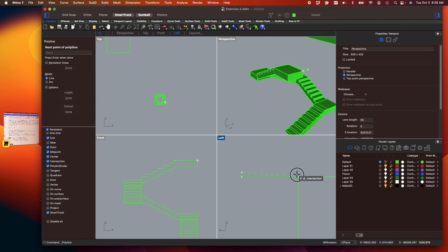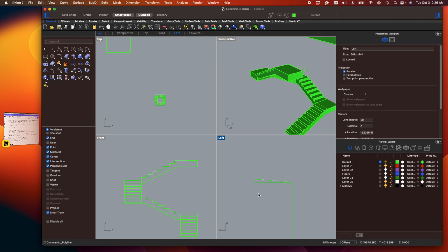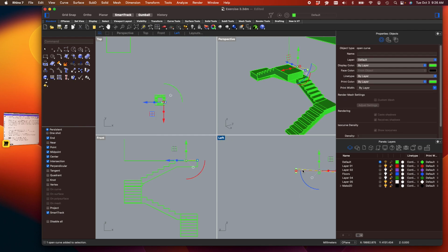All right, so we'll make a tiny triangle just to kind of help us out. Right. I'll decide my length of that ramp. So in my case, I just want to go to another landing. So I'm going to choose the same landing that I was doing. Perfect, right? I want the ramp to at least be that long. And then I don't know where that is actually going to hit, so I'm just going to draw a line vertically up that goes past it.